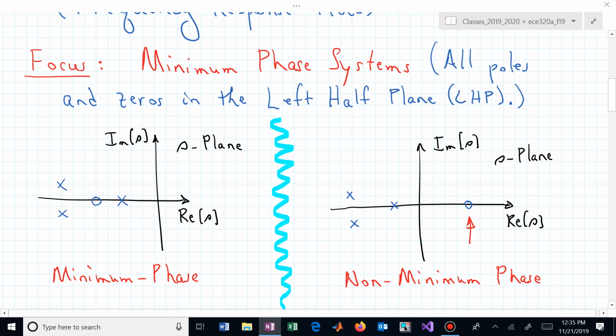What about poles and zeros on the axis? Poles and zeros on the imaginary axis we're going to allow. And for steady state accuracy purposes in a controls environment, we might like to put a pole at the origin. There's reasons to have, and some systems naturally have, a right half plane zero.